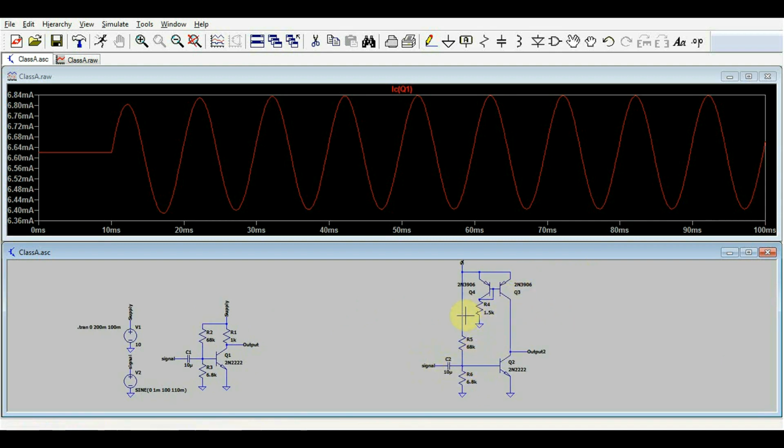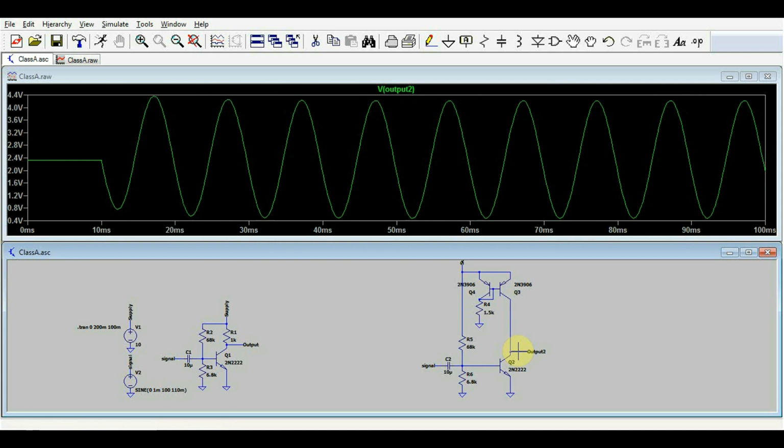We're still getting the same input signal, the same resistor divider to set up the operating point of our low side transistor, but in the collector we have this constant current source. The output is the same, the circuit behaves in the same way, but the constant current source gives us much better linearity when working with larger voltage swings. So when you're building a higher power amplifier, this is the sort of circuit you will be seeing. Having two transistors on the output doesn't mean it's a different class of amplifier. The class is determined by how the circuit actually works.